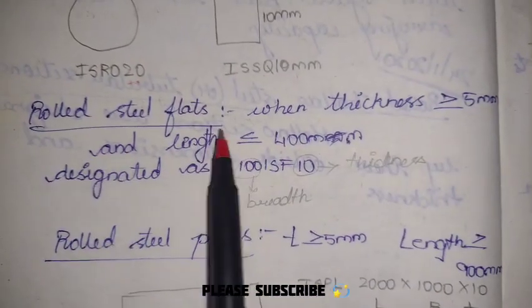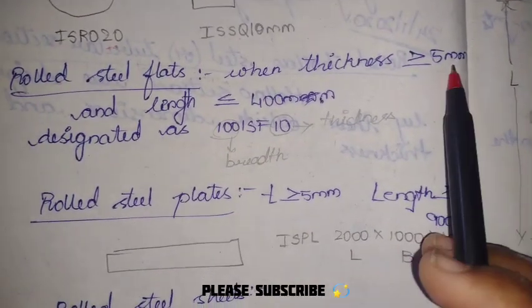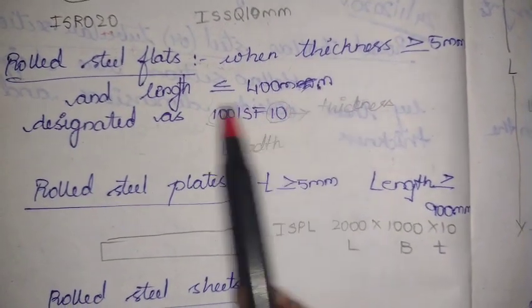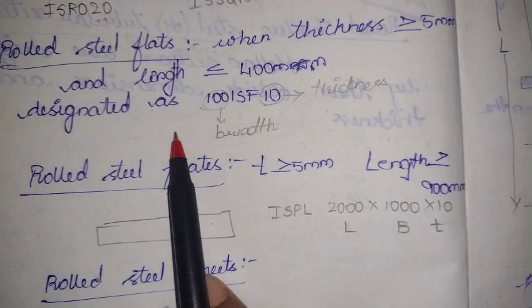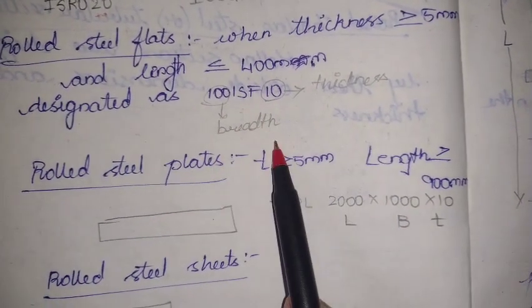Next we are having the rolled steel flats. Whenever thickness is greater than or equal to 5 mm, we are calling it as flats, and the length should be less than or equal to 400 mm. Here the designation is given by this one. This is the Indian standard flat. This is the thickness and this is the width.